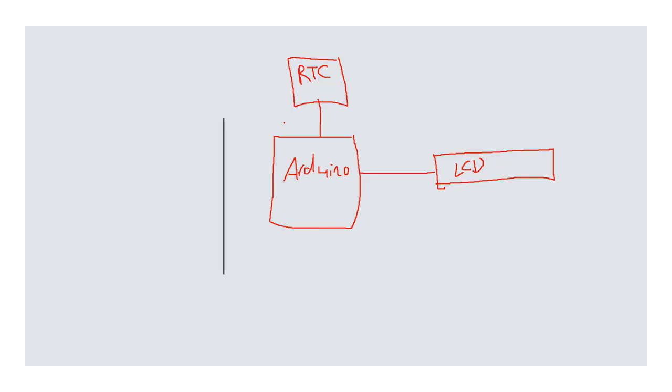Now, this is very simple. The 3 buttons will be connected to our Arduino board, and the input data will be sent, and the RTC will send real time and date data. The Arduino code will process the incoming button press with the RTC data and will display data on the LCD display. And we are going to connect a buzzer, and this buzzer will fire an alarm when the time comes for the patient to take his medicine.